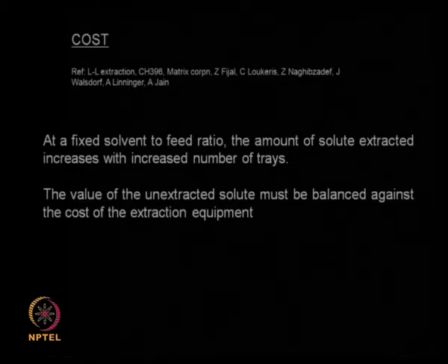Is it really worth extracting all the solute? It depends upon the price of the solute: is it a very value added chemical or is it a bulk chemical? If I have a very cheap solute which I need to extract, there is no point in adding an extra stage or another extra liquid extraction system to extract as much as possible, because the cost of the equipment may be much higher than the amount that is being extracted.